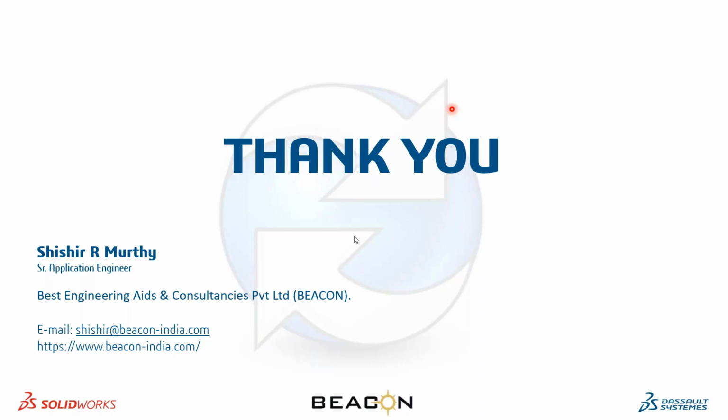In PDM, the editing is based on ownership. When it comes to assembly, I'm sure it's not like everyone is working on the same part. Let's say there is an assembly with 10 parts inside it. Each of these parts can be shared with respective users, who can take it as their ownership and start working on it. The assembly will still be available for all of them to refer to while creating or modifying those parts. In that manner, multiple users can easily work on the files inside the assembly. I hope that answers your question, Sachin sir.